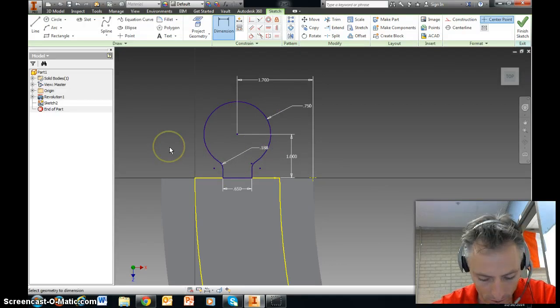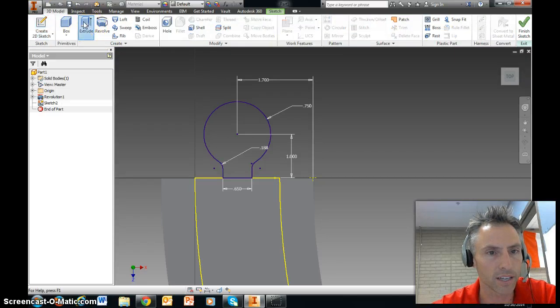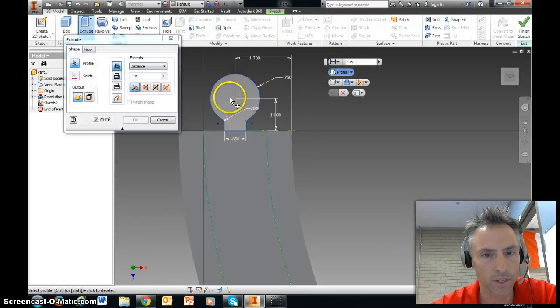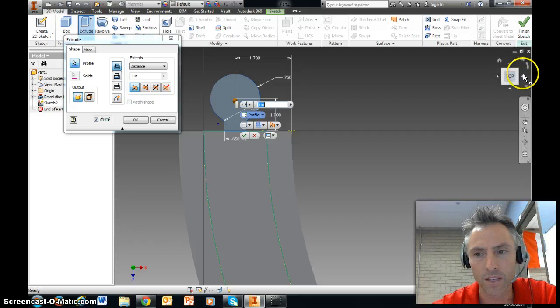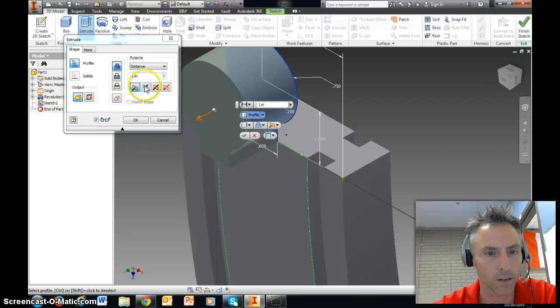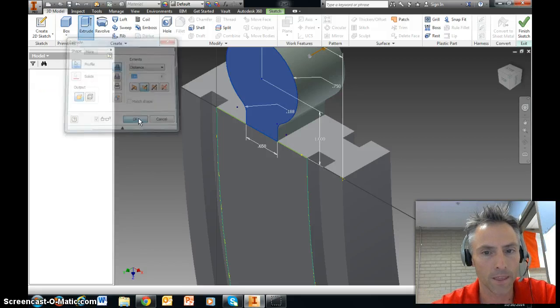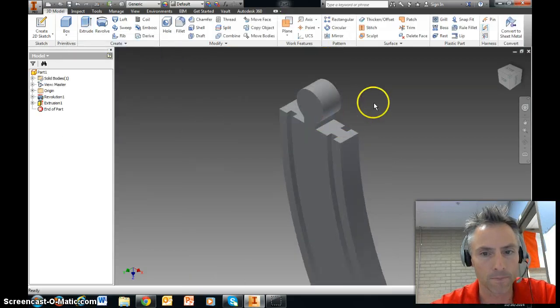There's no more flexibility. So it's done. What we're going to do is go to 3D model. We're going to say extrude, and we're going to select that. I'm going to tilt it to make sure we're going the right way, because sometimes it'll come at us, which it's doing. It was going to extrude up toward us. I don't want that. I want it to extrude back down. And it is 1 inch, just like I want it to be. So we'll say OK. And now we have a knob on that one side.